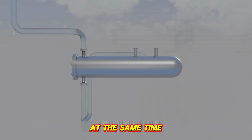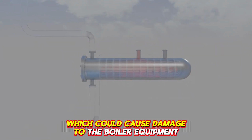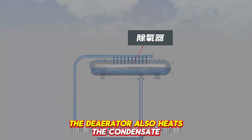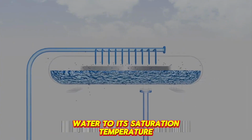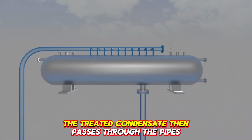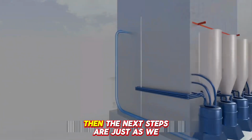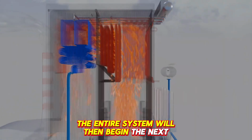At the same time, it also prevents the condensate from entering the boiler directly, which could cause damage to the boiler equipment. The heated condensate water then makes its way to the deaerator here. The deaerator also heats the condensate. At the same time, it can heat the water to its saturation temperature, removing oxygen and other gases from the water. This helps prevent equipment corrosion. The treated condensate then passes through the pipes to re-enter the economizer inside the boiler. Then, the next steps are just as we mentioned earlier. The entire system will then begin the next cycle.